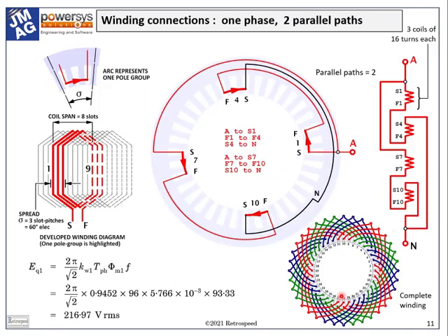At this point, we are ready to determine the stator winding. We can begin with the same winding layout that we used in the induction motor. That is a three-phase lap winding with 36 coils. There are 4 coil groups per phase.